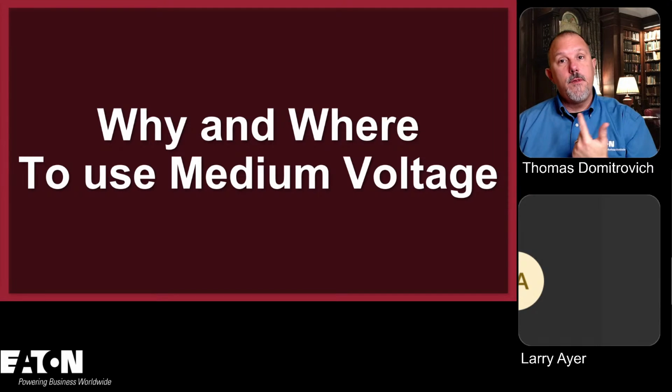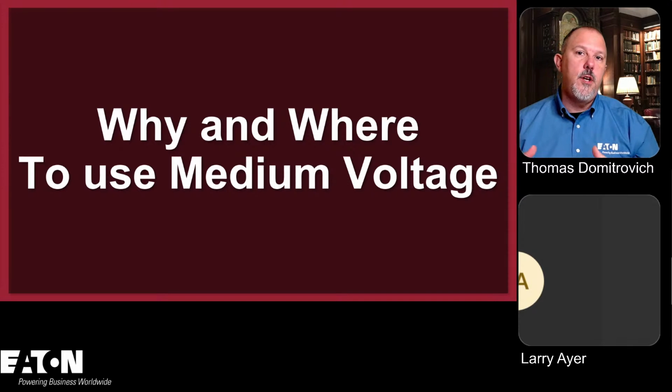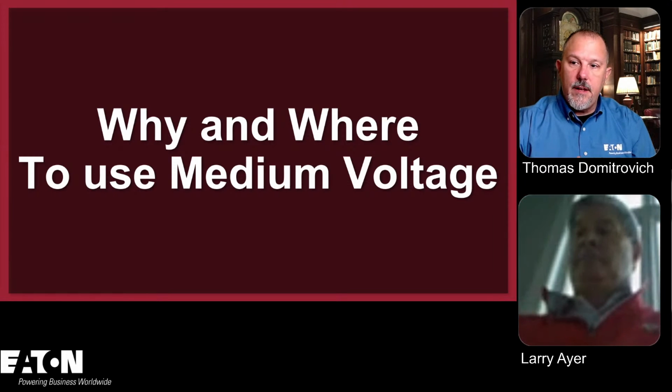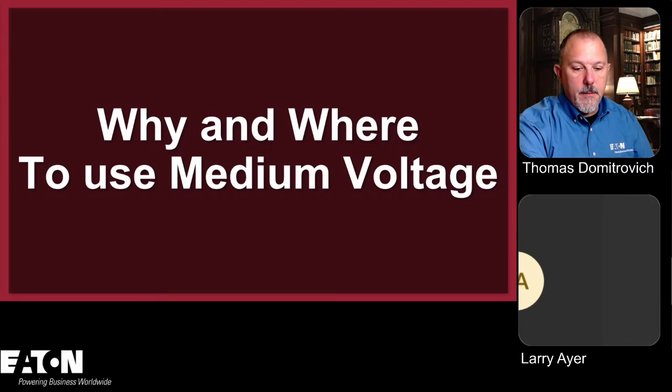They would bring the medium voltage around the ball field and then step down in smaller substations. So from a when-do-you-use-medium-voltage-equipment perspective, I agree with Larry in that it's all about when you have distance involved, when you're trying to take voltage across a campus, because you've got to think about voltage drops. And when I have lower voltage, my conductors are larger.